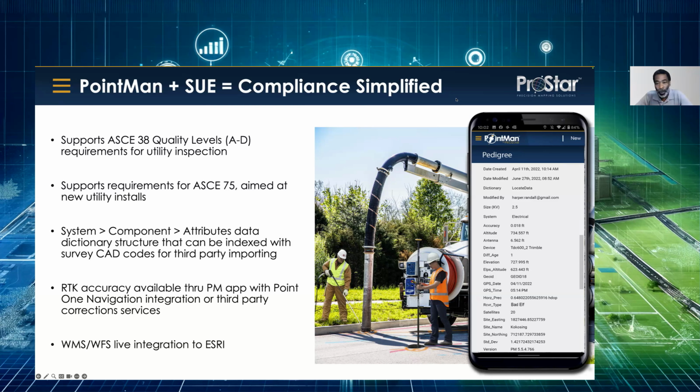Yes, so obviously I use PointMan often with electromagnetic detection equipment, whether that's Metrotech or radio detection. And you can actually go out, connect to the line, and collect XYZ data on the actual location of the line underground. And it's very accurate. Now, obviously, you're just locating the wire, but you're going to know exactly where that wire is. That wire is placed in proximity to the pipe that you're trying to locate, unless that pipe is steel or, say, copper, because obviously both of those conduct electricity. But you can basically collect the exact XYZ location of the underground facility without putting your eye on it.